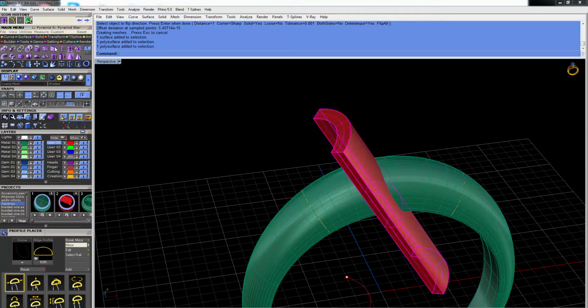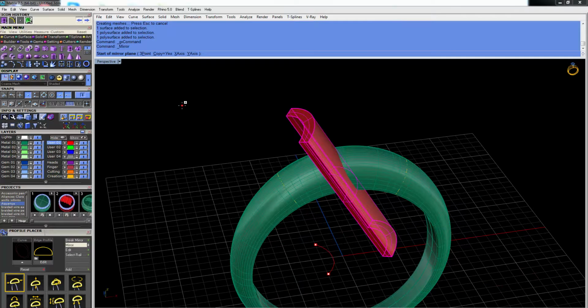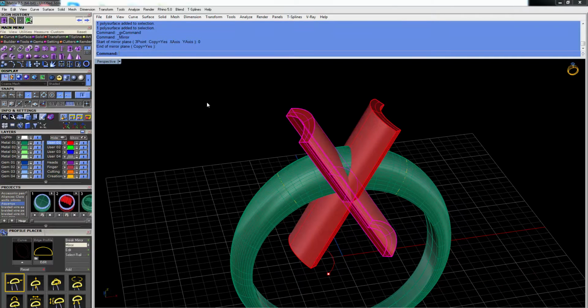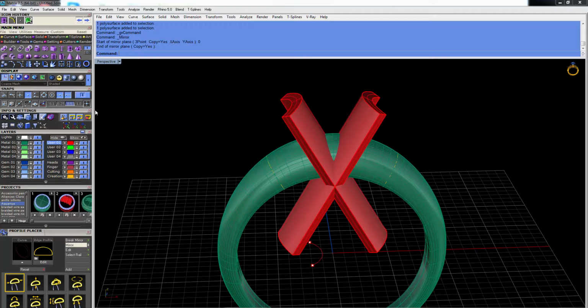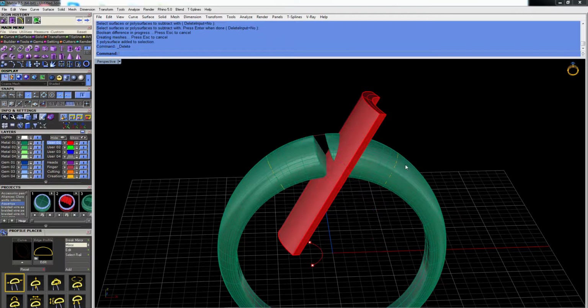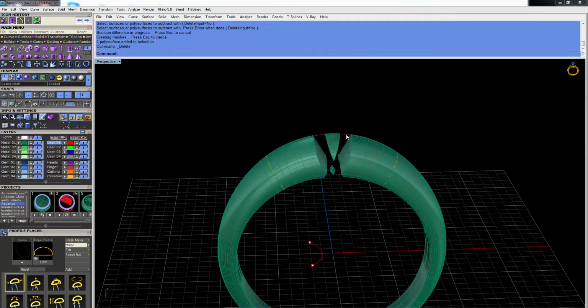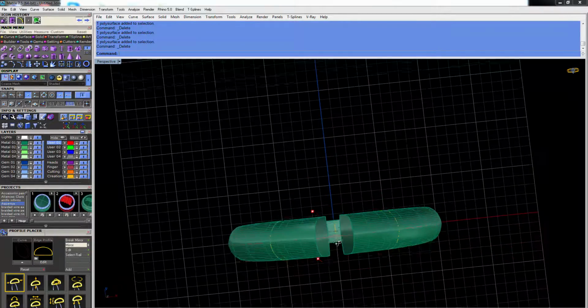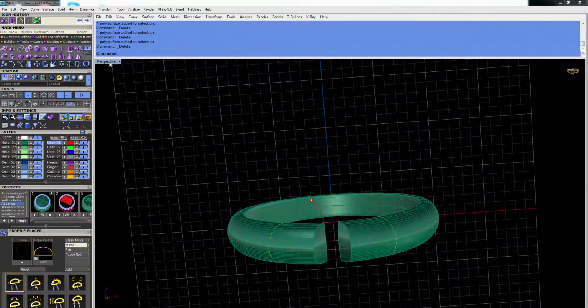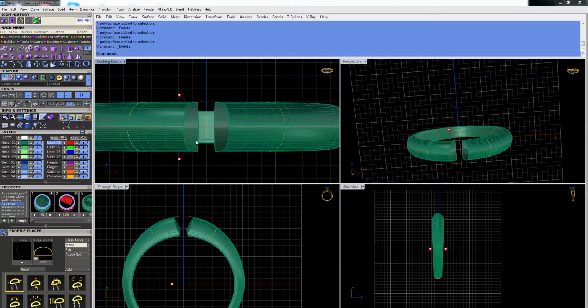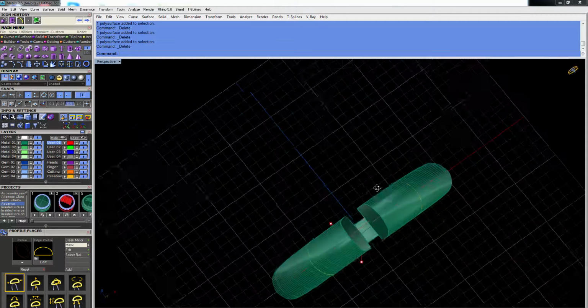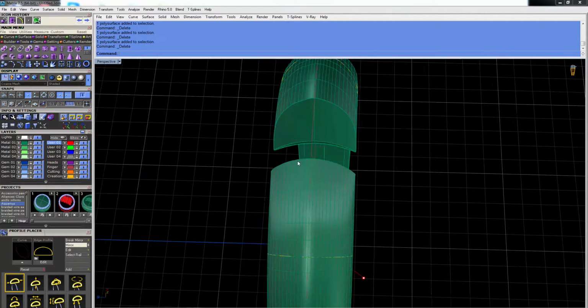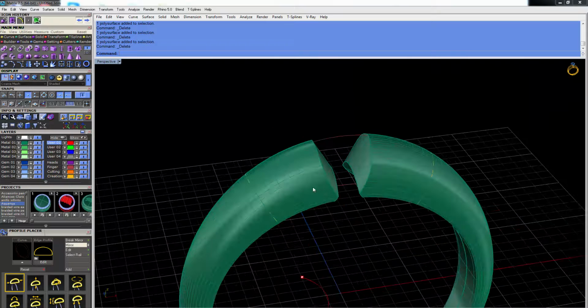So now I can select this last solid and make a mirror from 0 enter that way. Okay, so now if I make a Boolean difference as the first object and this is the second one, you see here I have a gap. Then if I do it again, I have this. I did an arc because I want this to look slightly curvy. Okay, it should be more than that, but anyway, it's okay. You see from here, it looks slightly curvy. That's what I want.